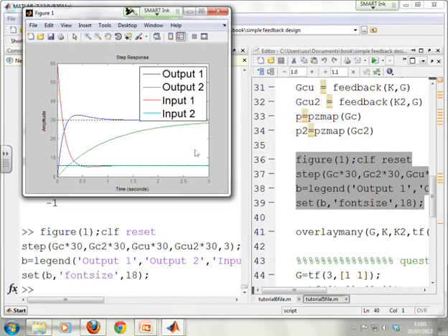So there you go, and you'll see with the proposed compensator, the input, the red curve, goes all the way up to 60 and comes down and settles down here at 6. That's because I've set this target as 30, that's why it's gone up to 60. Whereas the input with the heuristic, you'll see, has gone straight to the steady state value and stayed at steady state. A consequence of having this aggressive controller is you've got a very fast output response. You'll see there's a slight overshoot here that might or might not be expected. With the heuristic, much slower and smoother response.